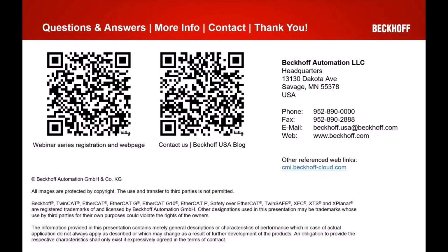Okay, some more questions about versioning. Yes, 4024 is 112, and even older, the 110. That's correct. And then 4026 via the package manager will work with 114. If you use virtual machines for your development environment, the mechanism for connecting a TwinCAT PLC and the HMI server is just ADS. It's our open communication protocol.